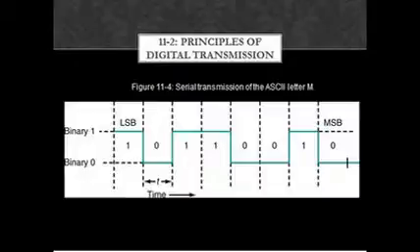Each bit is transmitted for a fixed interval of time t. The voltage level representing each bit appears on a single data line one after another until the entire word has been transmitted. For example, the bit interval may be 10 microseconds, which means that the voltage level for each bit in the word appears for 10 microseconds. It would take, therefore, 70 microseconds to transmit a 7-bit ASCII word.